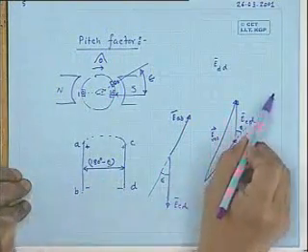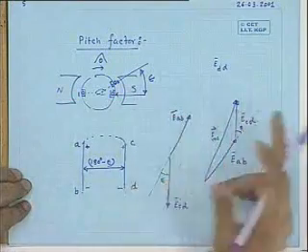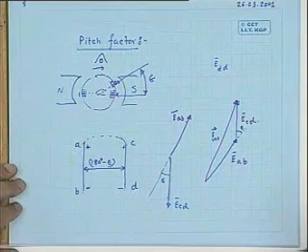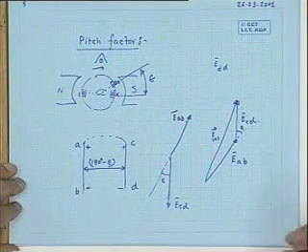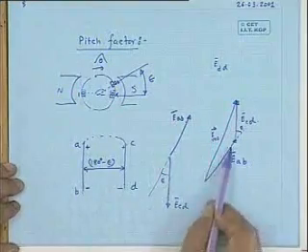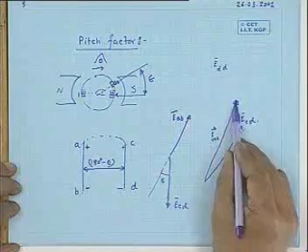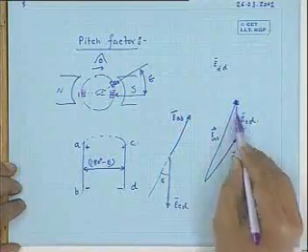If the coil span were 180 degree, then it would be just the algebraic sum, and you would have got twice BLV. Is that clear? So the addition of these two things gives you the voltage.